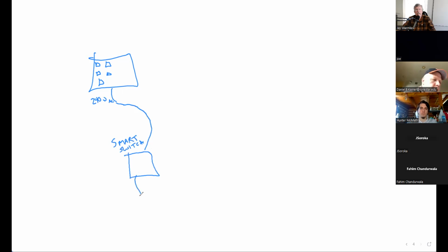I'm going to connect a battery bank into this. Now, the battery bank with this particular unit has microinverters built into it. So it can take AC power and convert it to DC, and it also takes the DC power and converts it to AC. Excuse me. So the battery bank is more than just batteries. It actually has inverters with it.